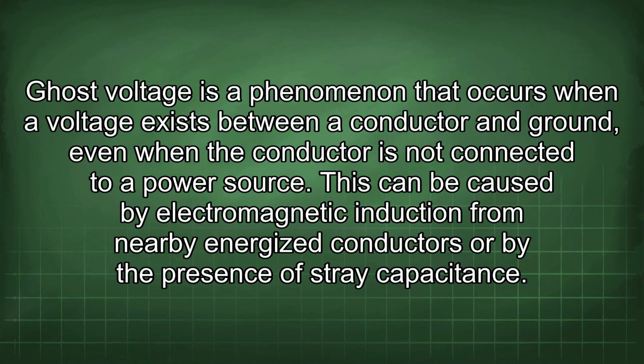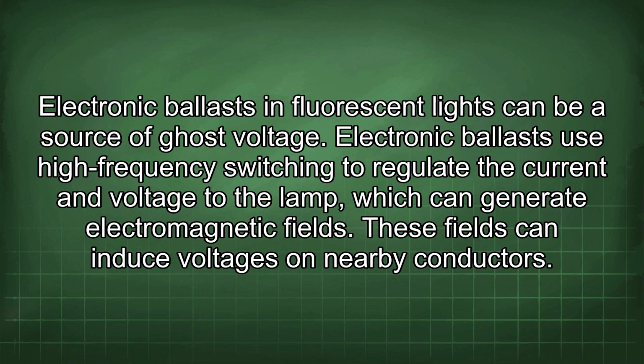Ghost voltage is a phenomenon that occurs when a voltage exists between a conductor and ground, even when the conductor is not connected to a power source. This can be caused by electromagnetic induction from nearby energized conductors or by the presence of stray capacitance. Electronic ballasts and fluorescent lights can be a source of ghost voltage.